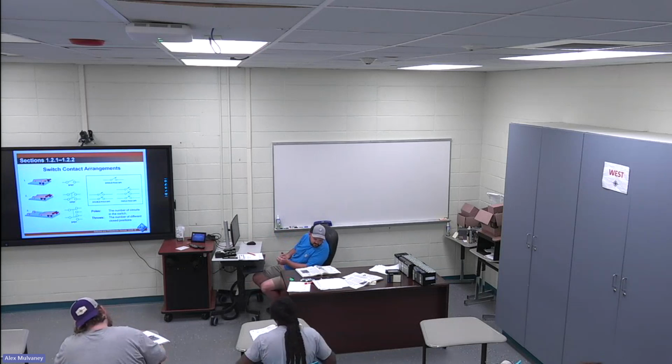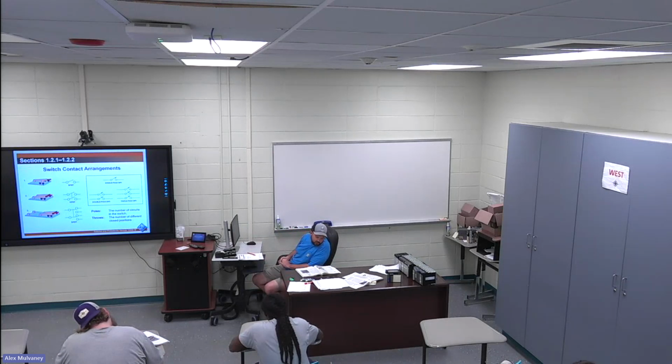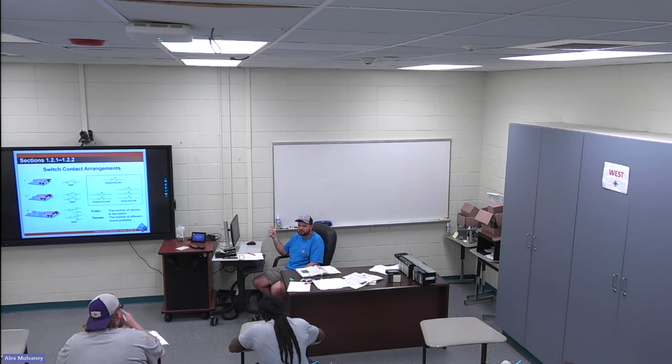Switch contacts 1, 2, 1. Second paragraph, second sentence is highlighted. Contacts are often coated with a conductive material to prevent oxidation and ensure low resistance contact point. I showed y'all that contactor out of my air conditioner with the pitting and stuff. There's a white grease, like a dielectric grease, that they can put in that stuff. If it has the grease in there, it will eliminate that arc, which will help with the pitting and also help with the contact. So a lot of times you'll see that white grease.